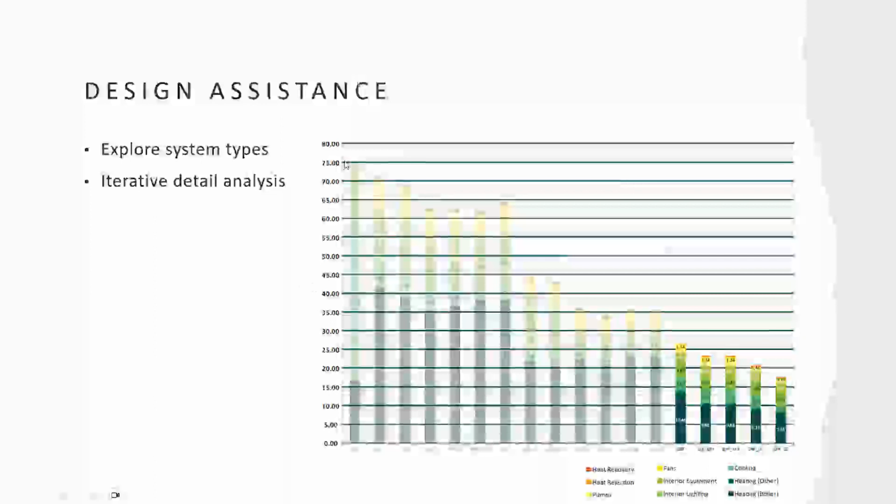So here we have our ideal baseline. Here's with an RTU, VRF, and just going down the line, testing different technologies, seeing the impacts, as well as then changing the operational parameters of those and trying to optimize them. And in a utopia, we arrive with a building like this, right? Use the least amount of energy possible while meeting all of its occupant comfort demands and criteria for the space types.